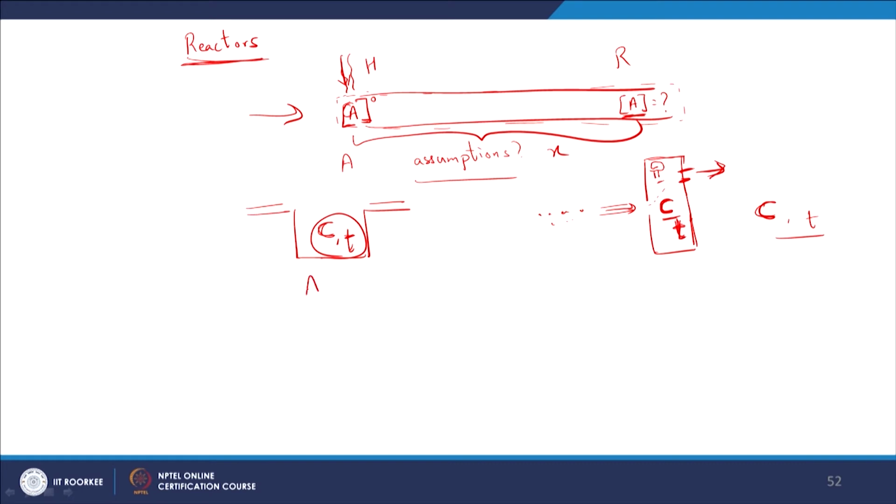So this is an example of your activated sludge process. I want to know the concentration either at equilibrium or more specifically how it changes with time in my activated sludge process, right. I want to be able to use this concept of reactors and then model concentration versus time, and so now I know that at equilibrium this is the concentration that is going to be, and this is going to be my design variable, right. So this is what we are going to look at. So reactors, again, they are relevant everywhere. So there are 3 ideal case reactors. Let us look at what they are.